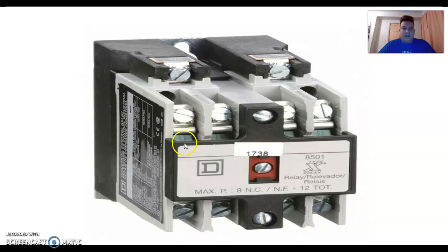It's pretty high for a control circuit, but it's really nice. And if you look right inside of here, what you're actually seeing is a symbol for a normally open contact. Well, if you take this top plate off and you loosen up 1, 2, and 3 screws, you could actually take this whole top plate off, which will give you access to the coil. This is the plunger that gets pulled in when the coil is energized.